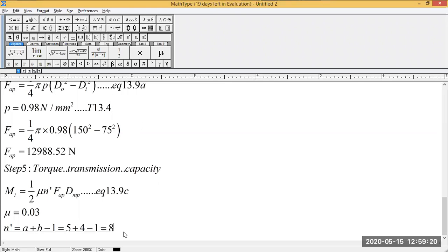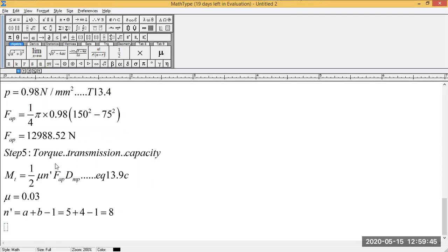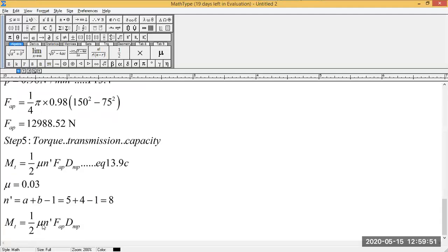So in the previous problem we got the number of friction plates, and that should have been an even number. Next time whenever we are doing this, we'll make it an even number. So make that from 6.4, which we got in the previous problem, to 8. Similar to this, this is the actual formula to find the number of friction surfaces, or vice versa, if you want to find the number of plates. You can revisit that if you have any doubt. For now, let's finish this problem.